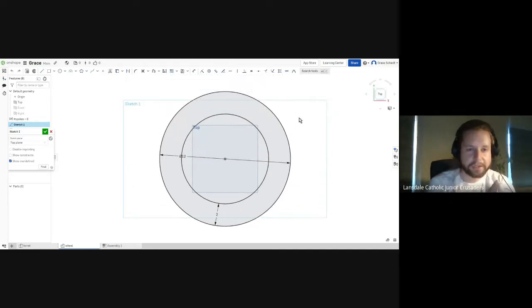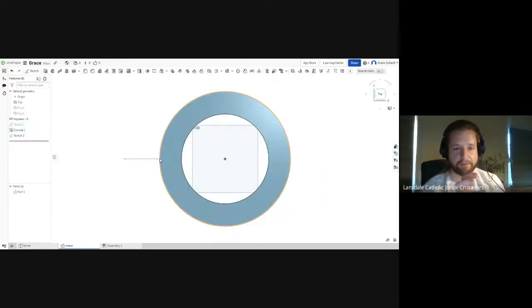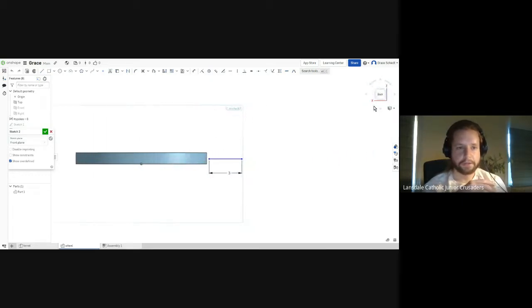And you're going to make a point, which is, do you see the little A up in the top? Little text thing? Yeah. Point is right next to that. So go to the left. There you go. So click that. And then create a point completely horizontal from the center line on the outside of the circle. There you go. Click. Perfect. All right, you've got your point. So now exit the sketch. And what you've done there is you've created a point that you can reference in that other sketch now. And this is what I mean by using other sketches to generate reference points for you.